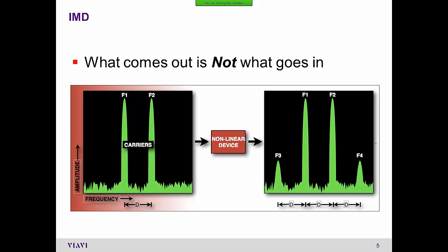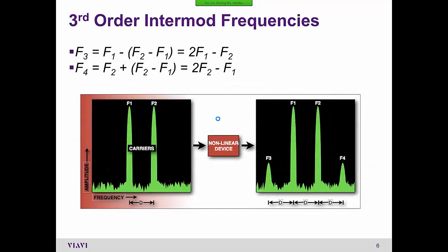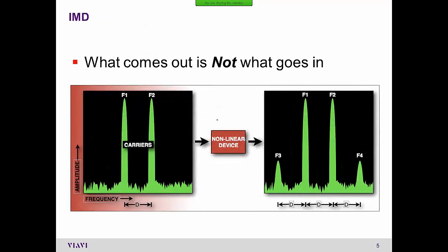There's all kinds of mechanisms for producing these nonlinear responses, either intended or unintended. So in an AM demodulator, you intend to do this. You intend to have these other frequency components produced by a nonlinear device. But in an antenna system, you don't intend that to happen, and you don't want that to happen.